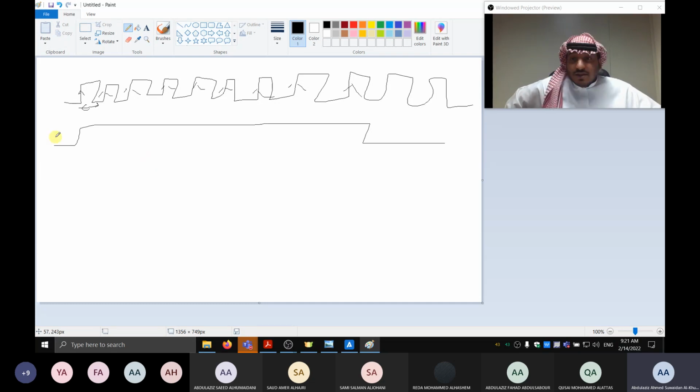Assume everyone understands. So you see, when you press a button, the system is running at 50 megahertz, so less than a microsecond. When you press a button and you are very fast, pressing once and then removing it, it seems like you have pressed for a very, very long time. So if you want to count up, it counts 500 times or 1000 times or 20 times, whatever. Everything is a random number. So that's an issue here. It's not counting up once.